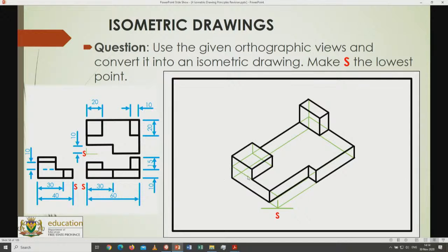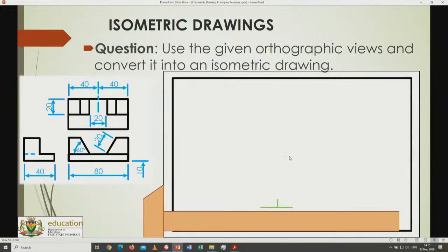Now if this line over here is soft enough, if you make use of a projection line, which is a type C line, it's not bothering and it will not be seen as a solid line or a seam, so therefore you can keep it. Please, if the examiner is asking to keep the auxiliary views and all those types of things, don't rub out the lines in terms of that.